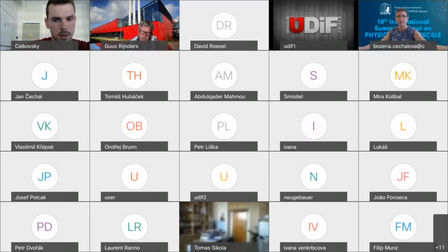And small deviations from the composition will still make it a good PZT material. So for the PZT, it's not a problem. For other materials, yes, it might be a problem. And especially when you also get closer to the edges of the substrates, where temperature and oxygen pressure control